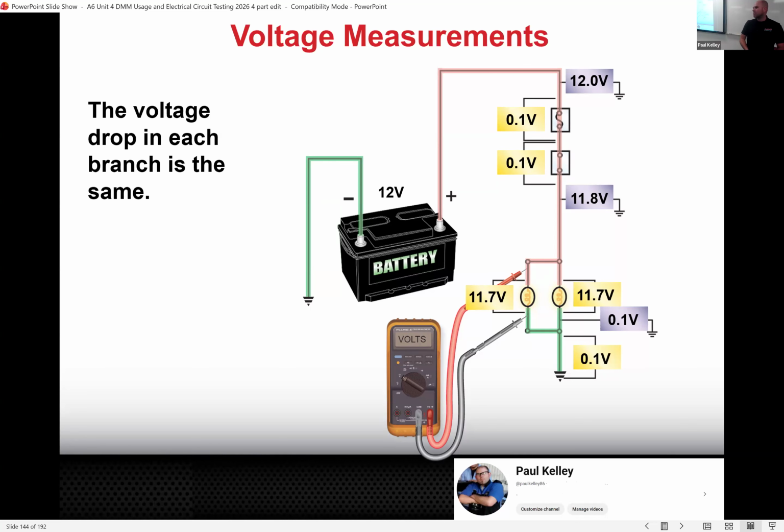The customer should never be upset because you explain this is the cost to diagnose it. And if they say, oh, all you did is plug in your fancy tool, you'd say, no, I don't. Look, I had to access these connectors and check for these voltage readings and study the diagram. We get paid for that. That's legit. But it needs to be correct though. You can't say, oh, it's the bulb, but then put a bulb in it, didn't fix it, and then say, oh, never mind, it was actually the fuse, because you charge for diagnosis time to make sure you had the right thing that was the problem. Make sense?